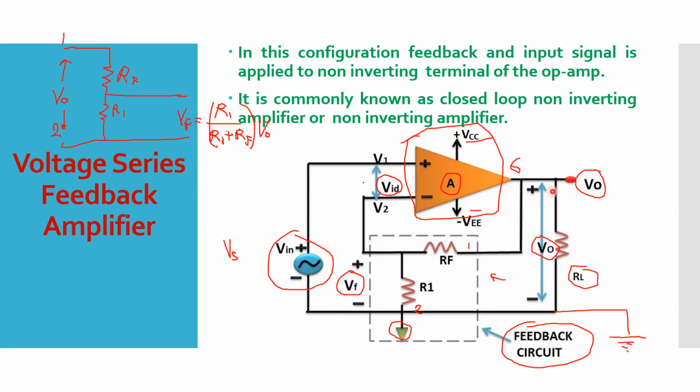If you apply Kirchhoff's voltage law, you can write your input voltage V in here. Let's start writing Kirchhoff's law, moving in this closed path like this. How will I complete the Kirchhoff law equation? I'm going from negative to positive, so I can say plus V in. Then here VID, it is plus and minus, so you'll say it is minus VID, isn't it?